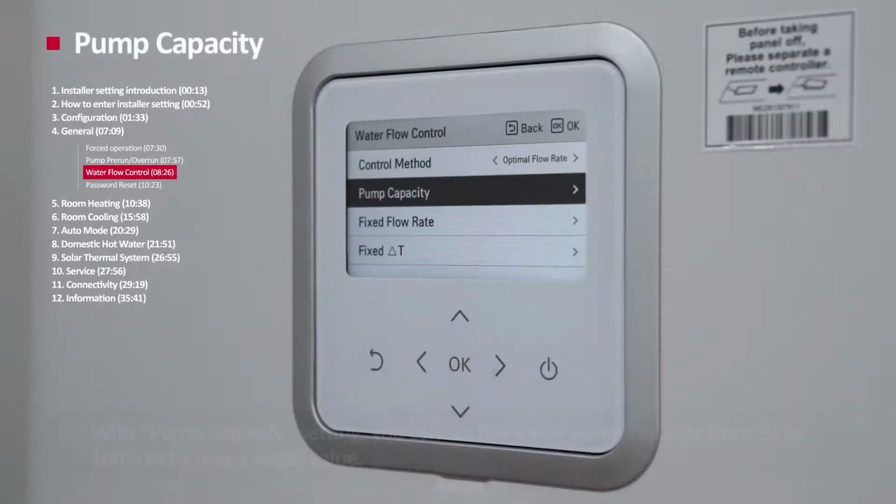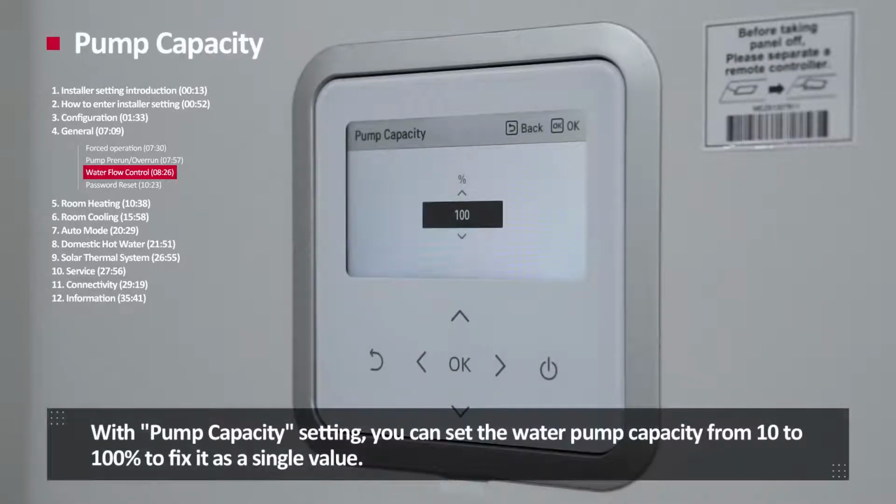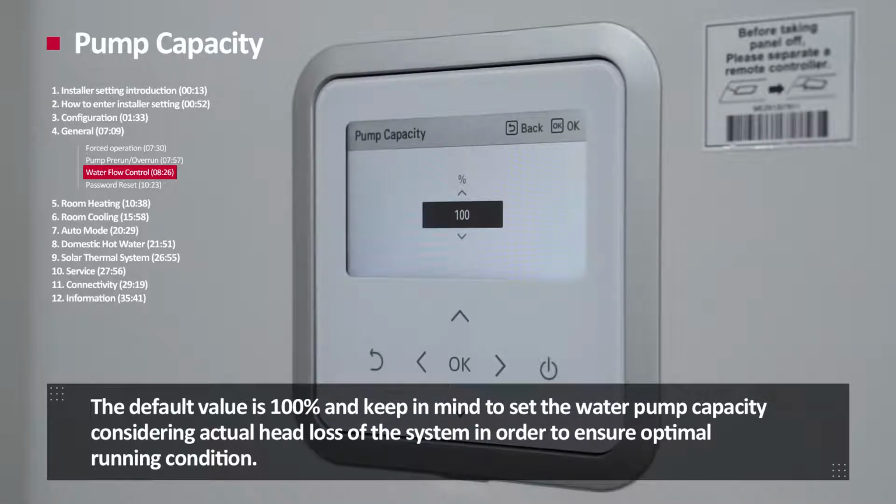Pump capacity. With the pump capacity setting, you can set the water pump capacity from 10 to 100% to fix it as a single value. The default value is 100%. And keep in mind to set the water pump capacity considering the actual head loss of the system in order to ensure optimal running conditions.